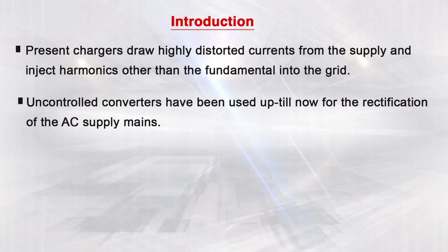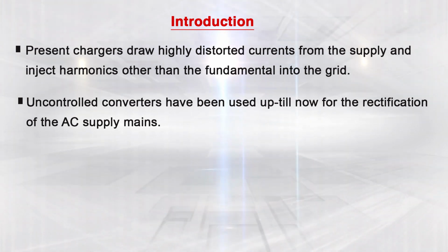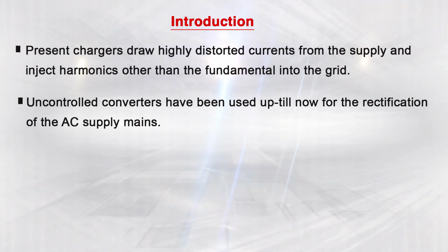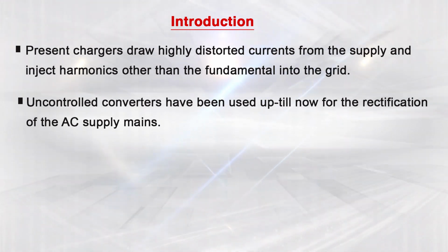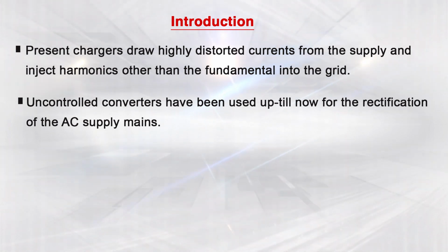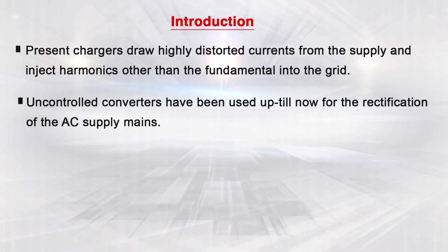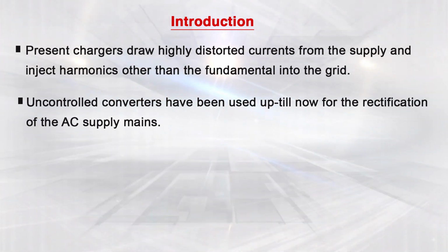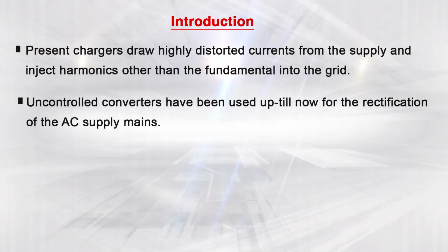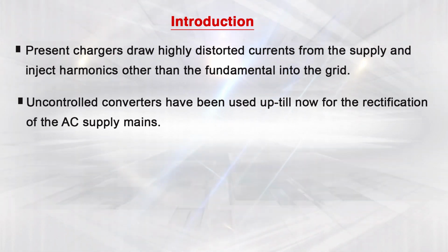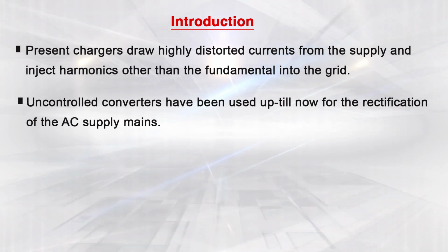So, we have two types of load: a stiff current load and a stiff voltage load. If we have a rectifier followed by RL, that comes under the category of a stiff current type of load. However, if we have a resistive load along with the capacitor, then this type of load is counted under the category of stiff voltage load.